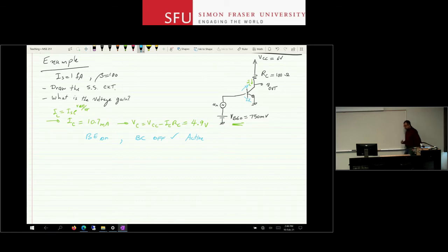And then from this point onwards, I'm going to deal with the small signal model. So here's the transistor in my circuit. I'm drawing the small signal model. So I said we get rid of the DC sources. First thing I do is that I draw the transistor. So the transistor is replaced with this model. Collector, base, emitter, right? The values are GM V pi. This is V pi, and the value of this resistor is R pi.